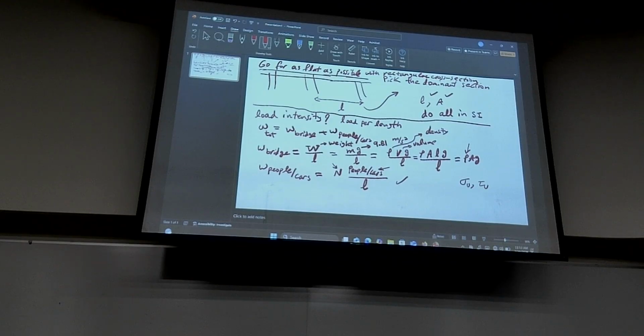All right, I see that you're done with your writing. So I would go to the bridge. I see that it has a certain number of pillars. Let's say I pick one segment. Perhaps the middle one is most dominant. I'll go with that. That's the length L. The cross section of that, again, I assume rectangular, with area A. I measure those or extract those by Google Earth, or the posting that is there, or calling the contractor. Any of those approaches. So L and A will be found out of this. So that's done.